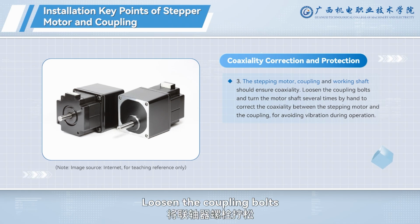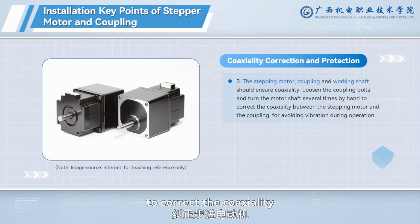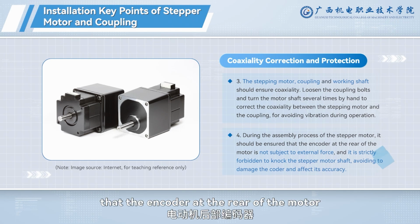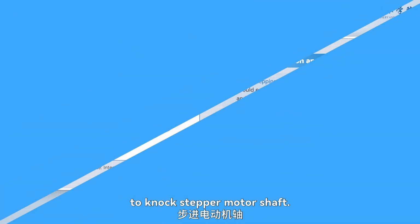Loosen the coupling bolts and turn the motor shaft several times by hand to correct the coaxiality between the stepping motor and the coupling. 4. During the assembly process of the stepper motor, it should be ensured that the encoder at the rear of the motor is not subject to external force, and it is strictly forbidden to knock the stepper motor shaft.